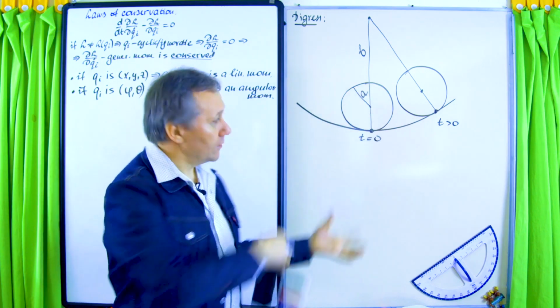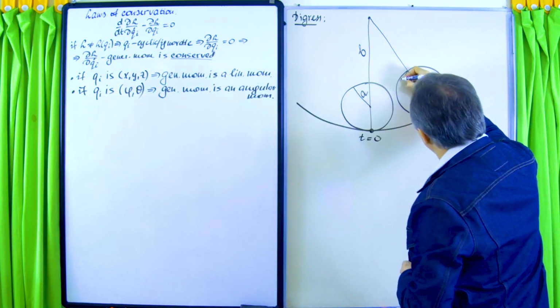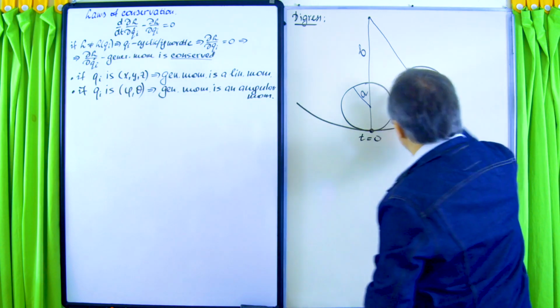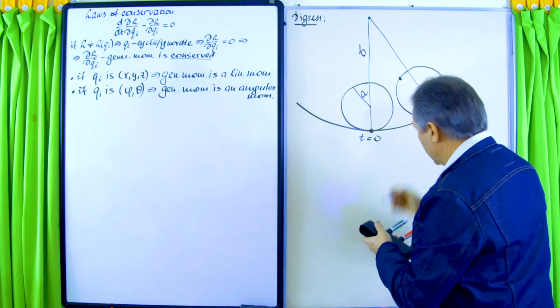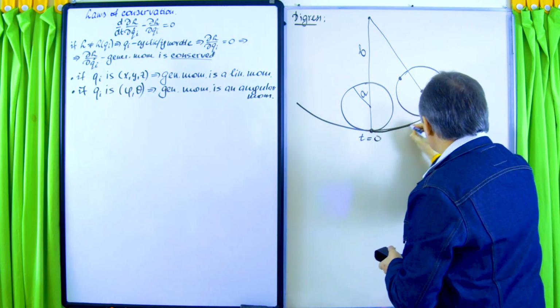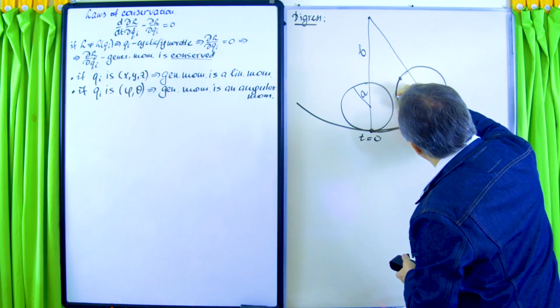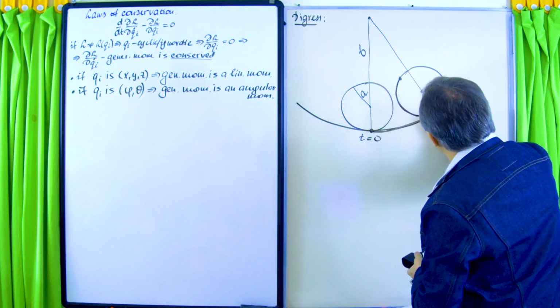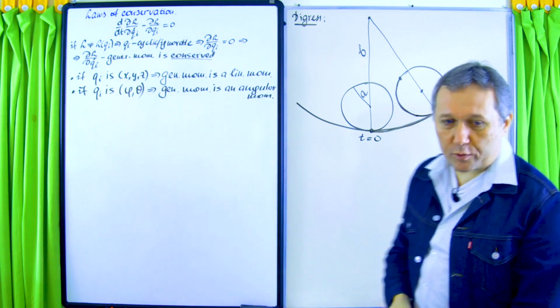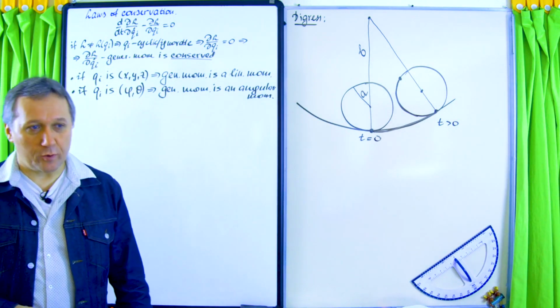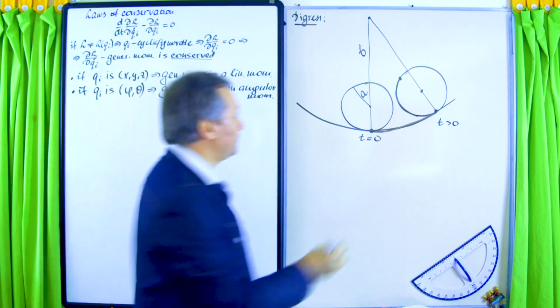After displacing the object, the point of contact will be somewhere maybe over here, so this point will move over there. As a result, this arc length must be equal to that arc length. Basically, that is the no slipping constraint, drawn on the diagram, right?